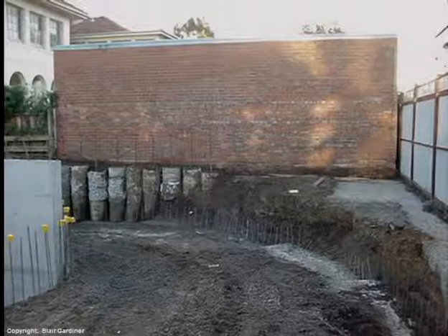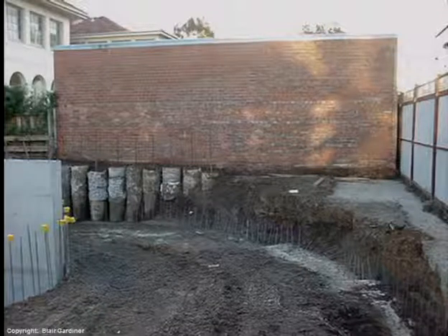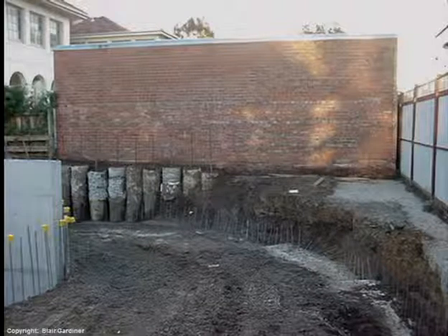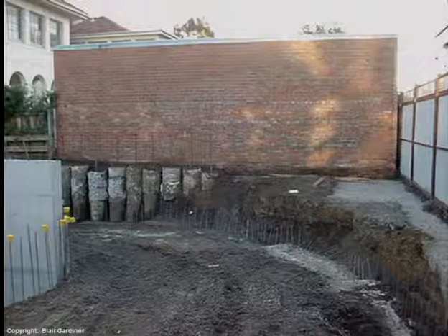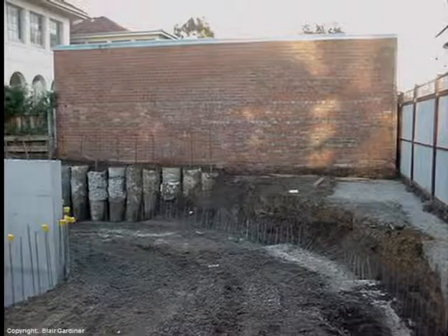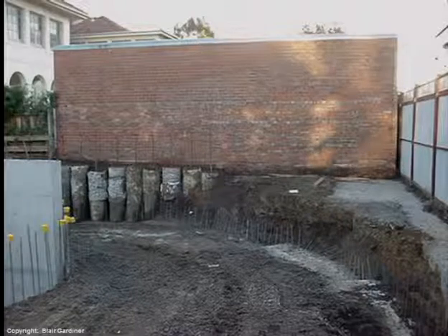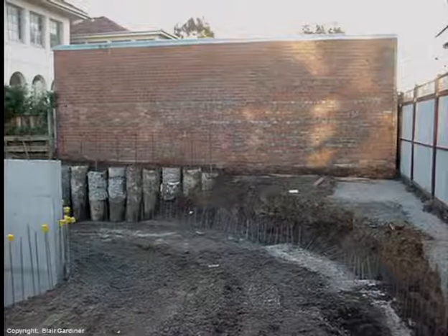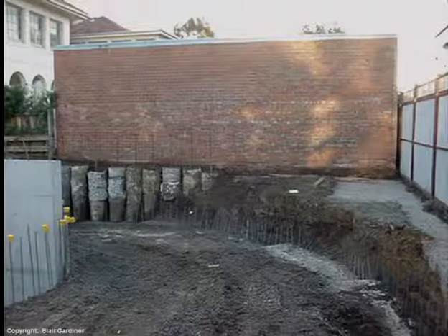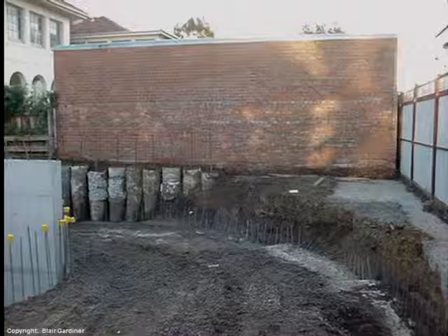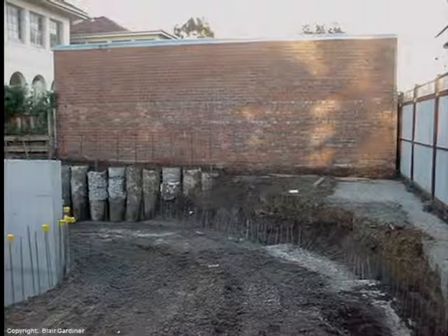And with my engineer, I would have designed a structural system that would support that building. Even though that's not part of my project, I've still got to account for maintaining the structure of the neighbour. So you can see with that line of influence, that load from their footing, you've taken away their support. So that line of influence is going into a void now. So you've got to transfer the load back into the ground, and that's your responsibility to do that.